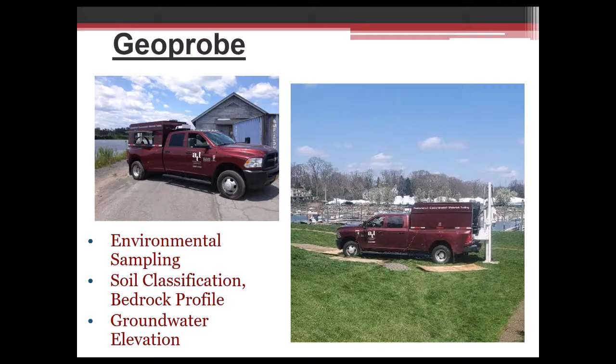What we actually found was the groundwater never came up when it rained, and that the leaking into the building was actually caused by the roof drains having eroded away in the basement. And so it was rainwater, but it wasn't coming from the ground, it was coming from the pipes inside the building.